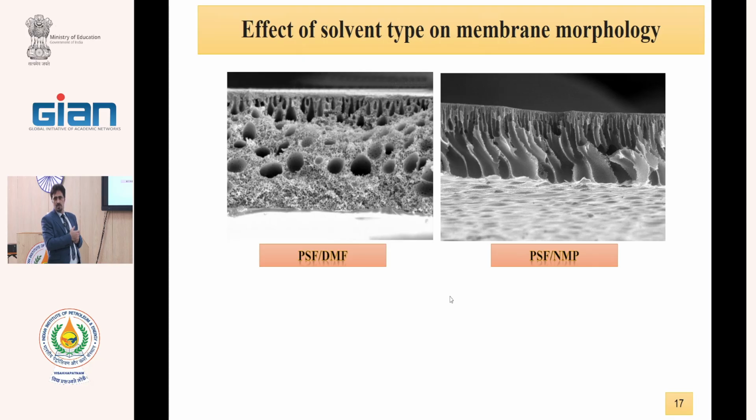Ceramic polymer membranes have 3 or 4 layers, but UF and MF membranes usually have 1 layer. But some Nafion membranes have 2 layers. When we see the cross-section of a Nafion membrane, we see it is 2 layers. Our RO membranes have 2 layers, 1 thin layer and 1 thick layer. But in dual layer membranes, 2 different polymers can be coated.